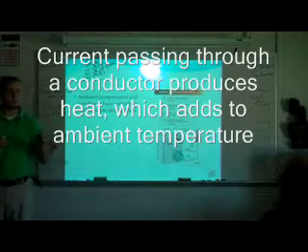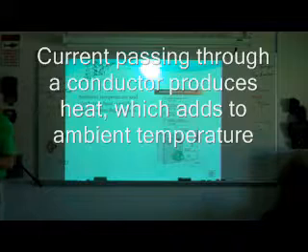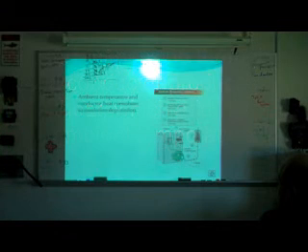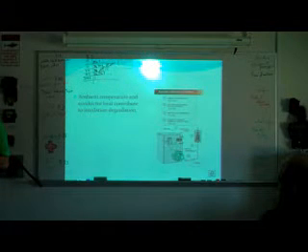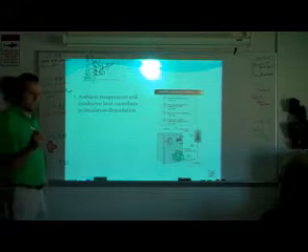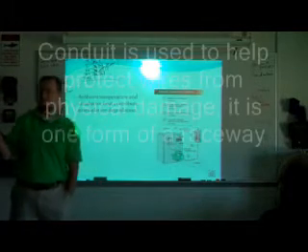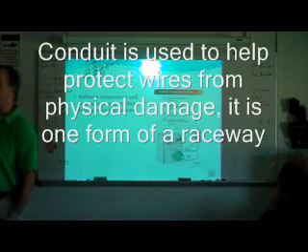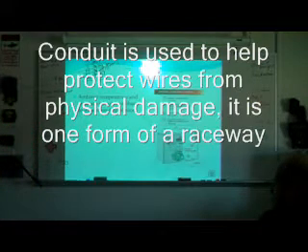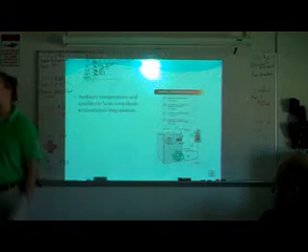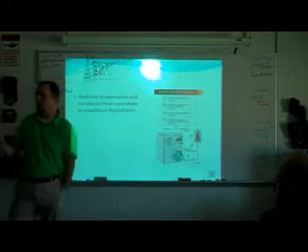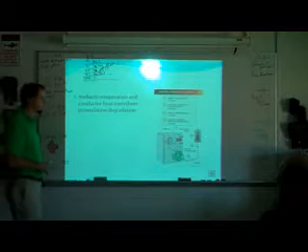In houses, the only place that this would really be a problem would be your services, because that's about the only thing that's actually run in conduit in a residential setting, a service or a feeder. But in an industrial setting, almost everything is run in conduit, because you don't want it getting hit or stepped on or cut or broken. So everything's run in conduit, and this really comes into play here.